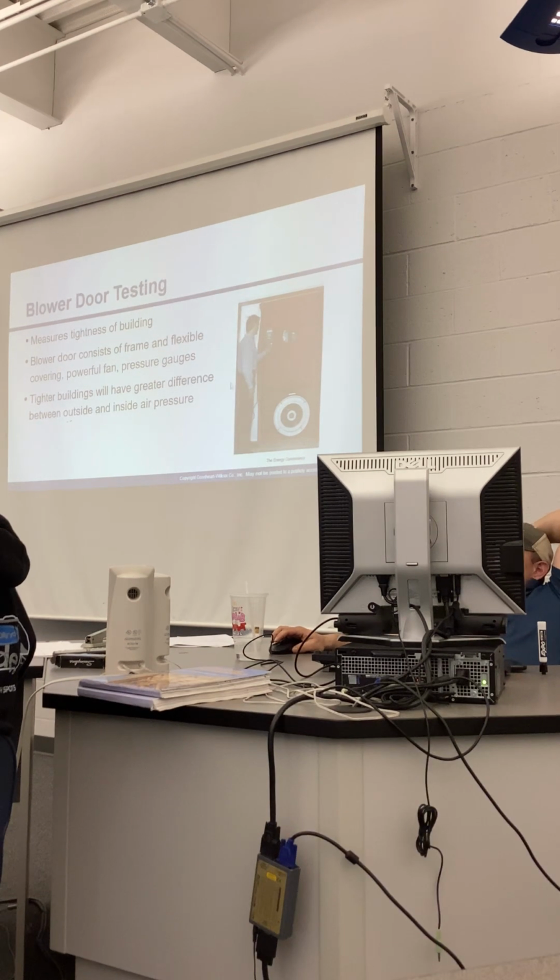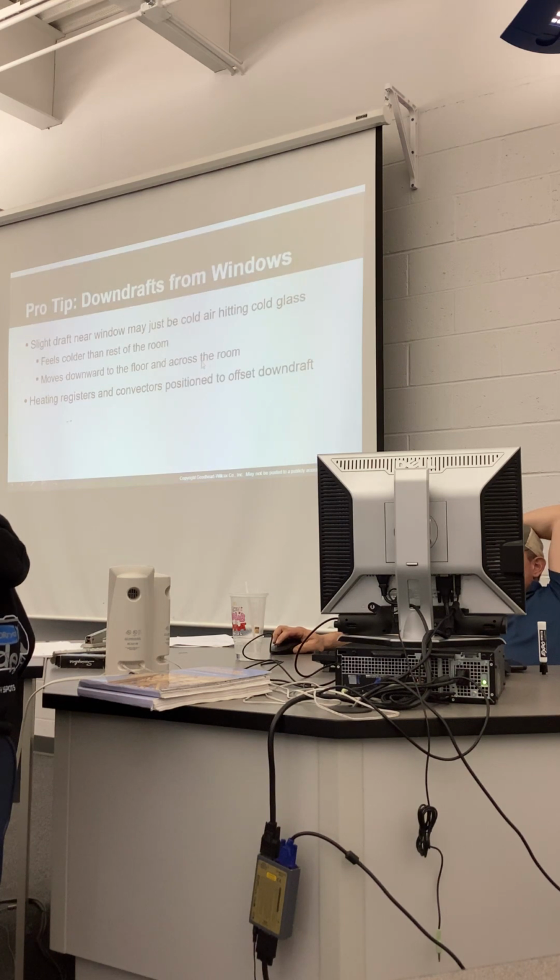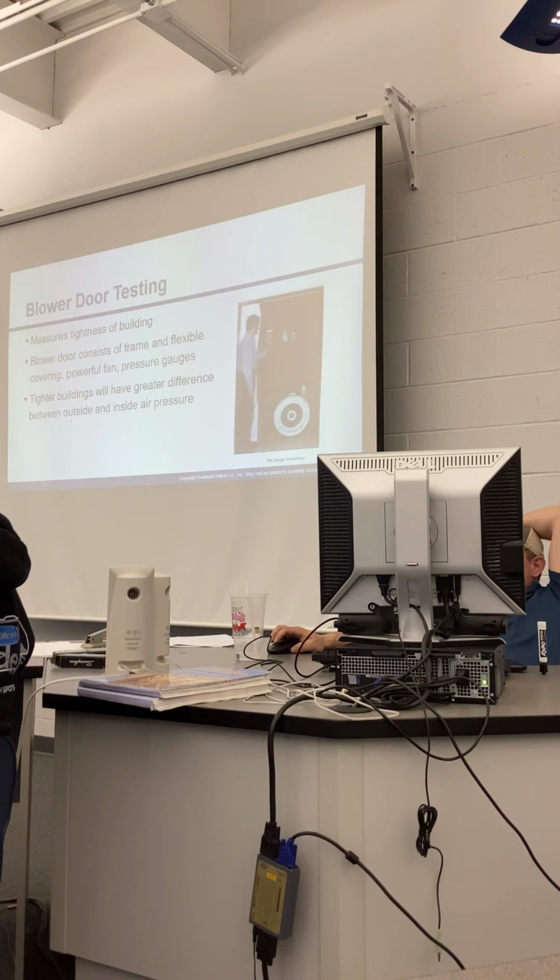So we're gonna do this. I've got 2 of these. These are blower door tests. We do this in green construction next year. We could also do it in weatherization, but it is how we test the house to see how well it's the air infiltration. It's mainly for air infiltration, not insulation, but air infiltration.